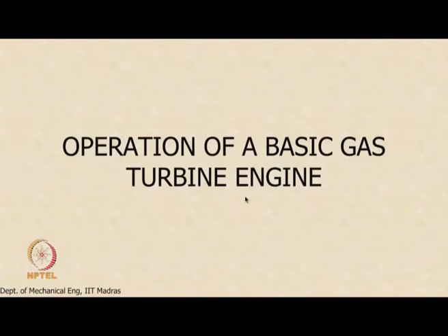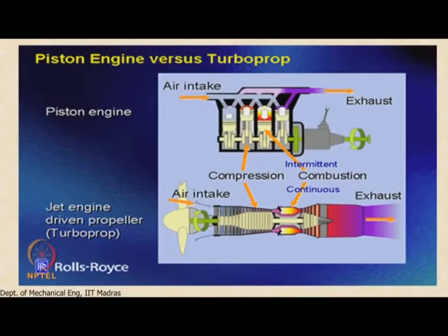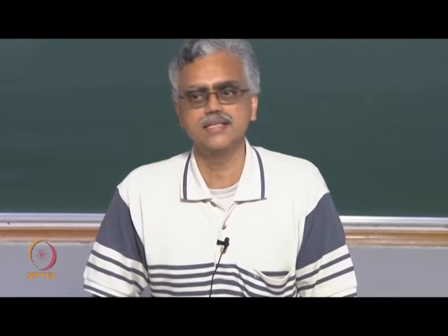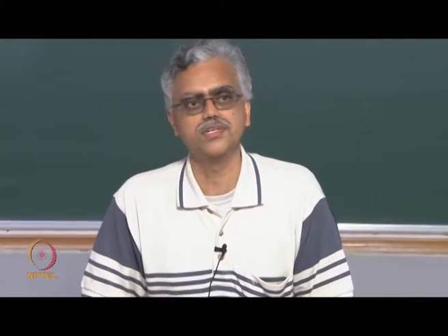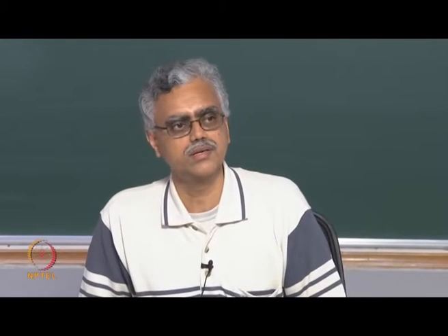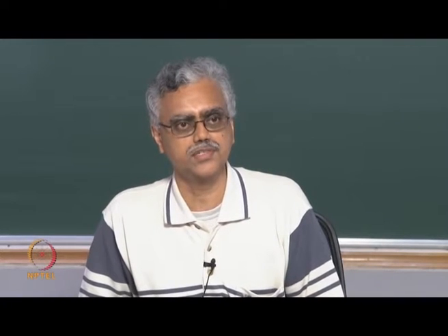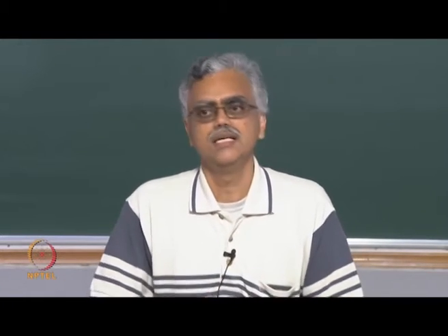So, now we will take a look at the operation of a basic gas turbine engine. Okay? So, here we are showing a comparison between a multi-cylinder piston engine and a gas turbine engine. Remember, both the engines have to do pretty much the same thing. From a thermodynamic perspective, you have to increase the enthalpy of a gas, so you increase the pressure and you increase the temperature. You increase the pressure by compressing the air, and you increase the temperature by injecting a fuel and burning the fuel in the airstream. Both do the same operation, but in a different manner.